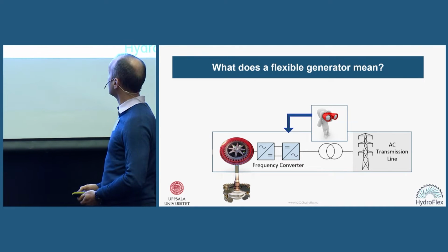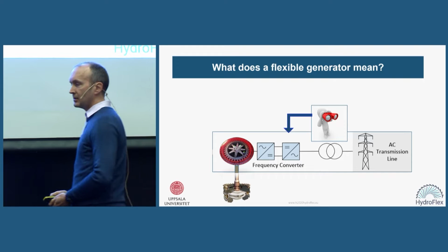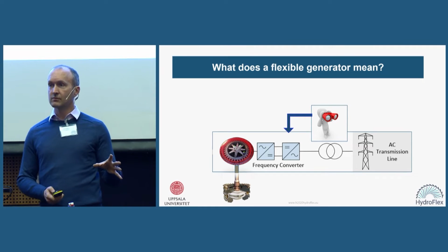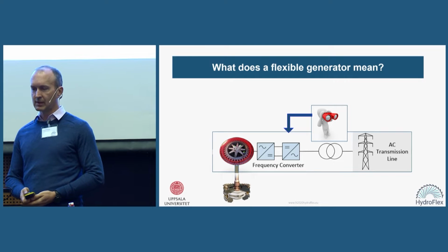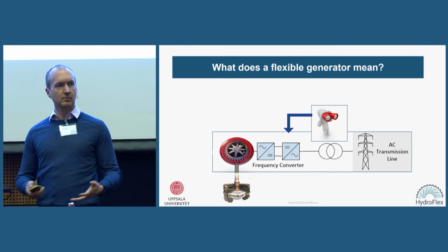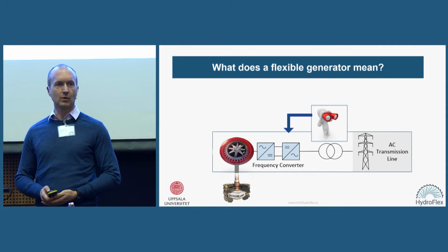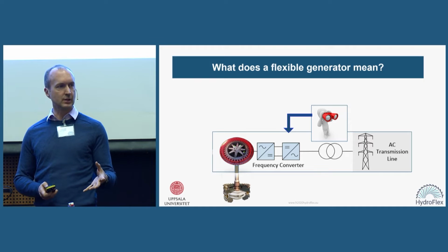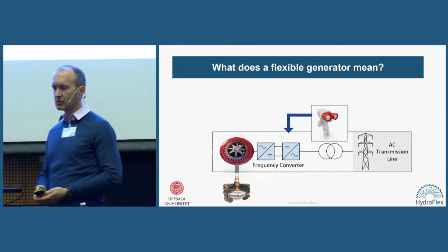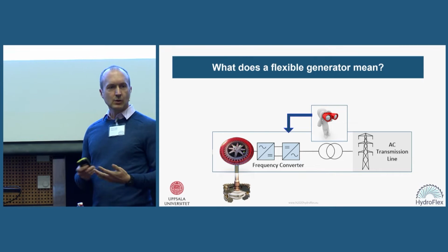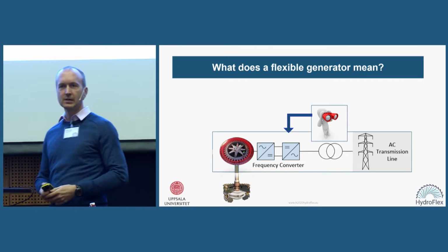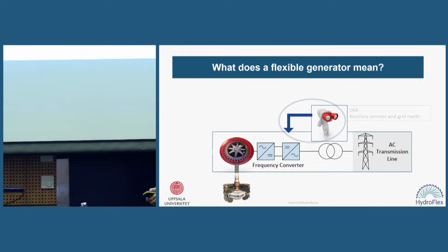So this is a figure of what we are talking about. We have the transmission system on the right here. We would have a transformer typically. We will have the converter, and that's not a standard component for the powers that we're talking about, hundreds of megawatts. Then we have a generator, and these generators could be purpose-built for variable speed, or typically we might reuse our old generators. And the question is, if we reuse an old generator, how does that live with a power converter? And then we have the other systems there as well, the turbine that you see. Then the question is also how to control this machine. So you have this man with binoculars looking into the grid and saying, okay, what does the grid need, and how do we want to control our machine in order to support the grid?